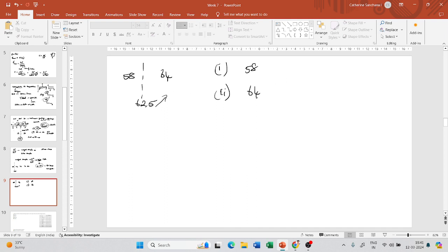Let us say he thinks the maximum temperature to which the bitumen can be subjected is 64 degrees Celsius, so he's going to use it in a place where the pavement temperature is 63 degrees Celsius. Now what will happen? Your pass fail temperature is only 62.5 degrees Celsius. As temperature increases, your bitumen will become even softer, so the G star by sine delta value will become less than 1 kPa.